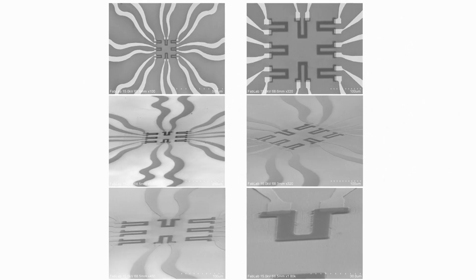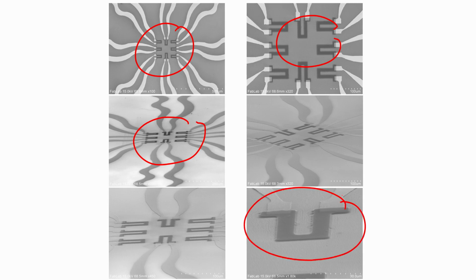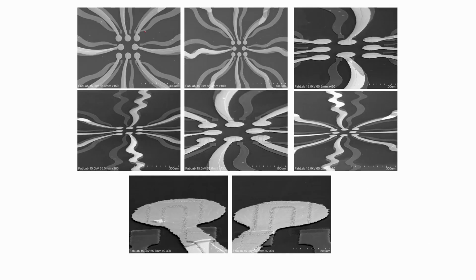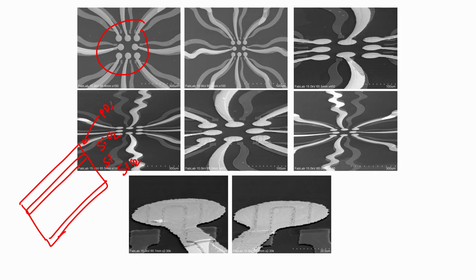You can see here now we have the strain gauge array, this is the top view, and the cross sectional view of the strain gauge. This is a SEM image, and you can clearly see a single strain gauge. Now, these are gold pads, you can see gold pads on insulator on strain gauge. So, what does it mean? We have a substrate, we have an oxidized silicon wafer, SiO2, we have silicon, and this one is our PDMS. On PDMS we have this strain gauge.